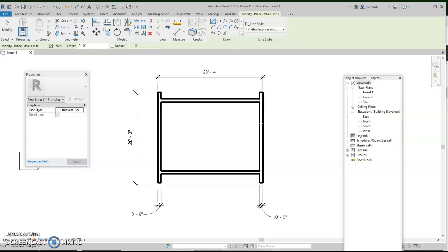So my red lines represent those super, super thin lines, light lines, when you are drafting manually. It shows the footprint of what you were thinking, how you arrived there. And you save it as red line sketch. You can always turn off that layer so you can no longer see that layer.